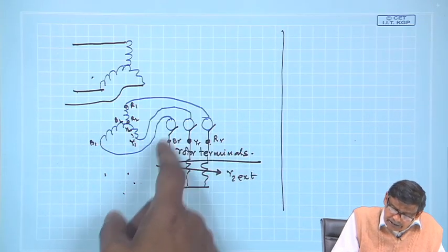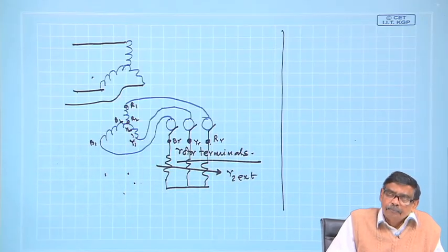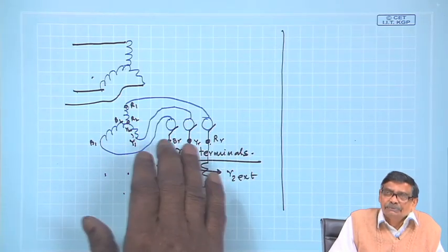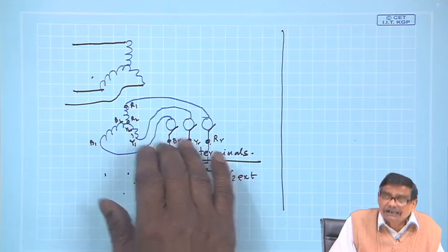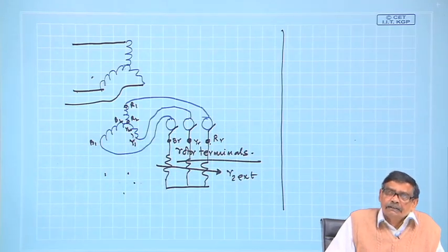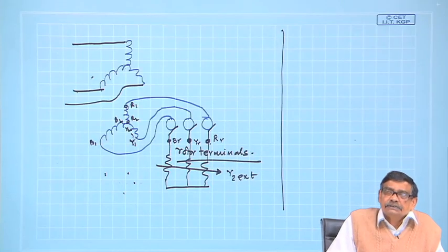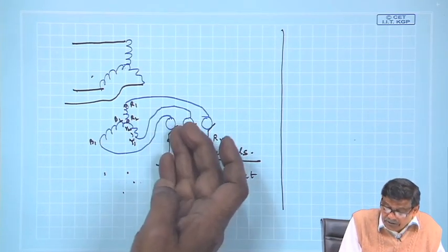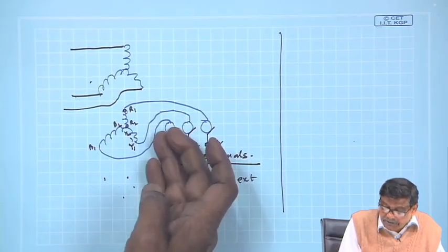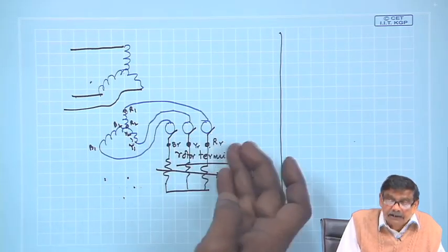While the slip ring and brush arrangement is a very nice one, it is also one of the things maintenance people won't like, because the brush has to be replaced for regular maintenance. Brush will wear out because of the friction between the copper ring and the brush.